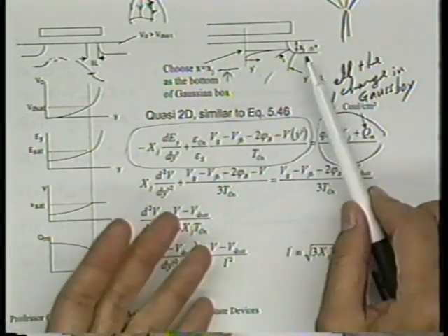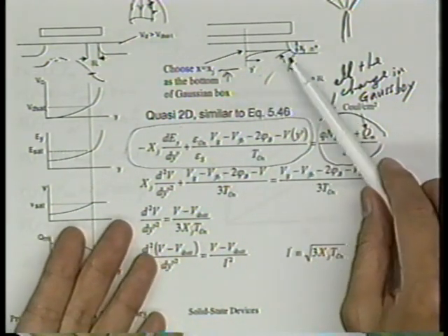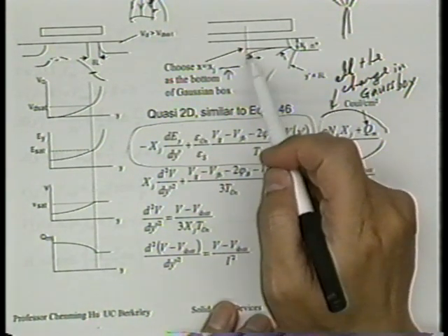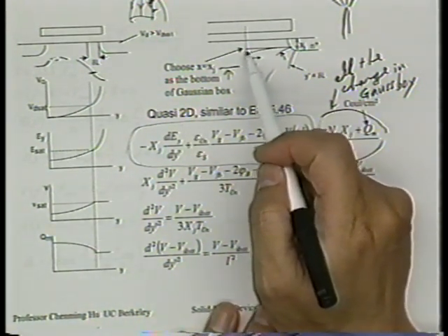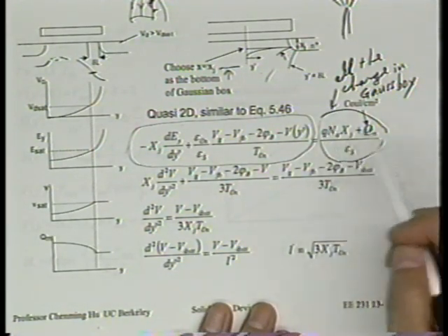And this can also be verified, by the way, by just solving the Poisson equation using a 2D Poisson equation solver. If you've done that, you will find there's always an electric field line fairly parallel about the junction. So for that reason, we take the approximation that we can find such an electric field line that's more or less flat to the surface about the depth of xj.